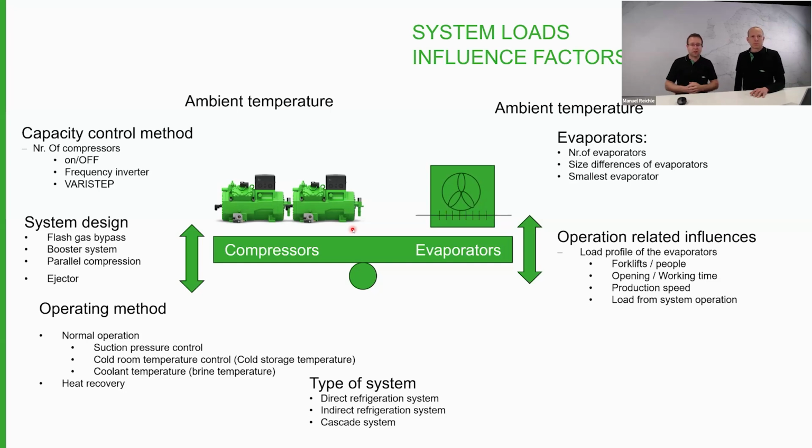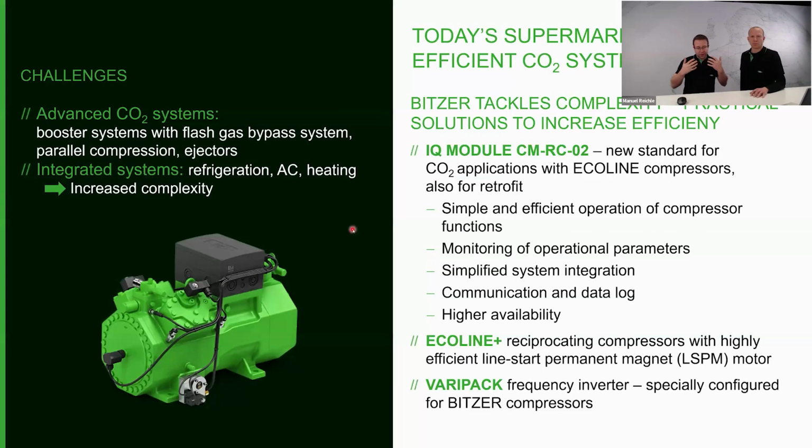If there are forklifts, the load for the rack system in a supermarket is quite different between opening times and closing times. When the temperature in the supermarket is reduced during the night, the demanded evaporator capacity is lower, then they put the fences down, or they have closed anyhow already. The people don't open or bring any additional heat inside, which has a big influence on that.